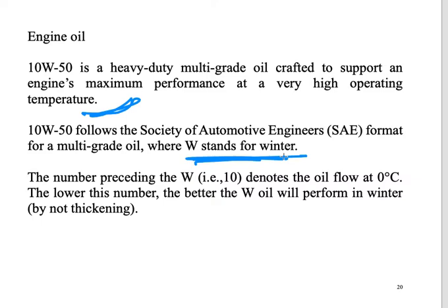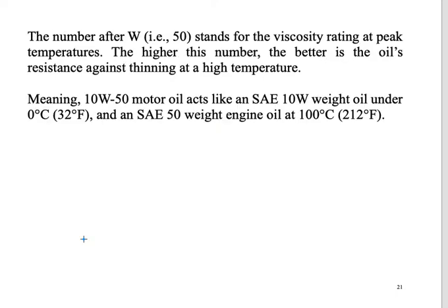So the number preceding the W denotes the oil flow at 0 degrees Celsius. The lower this number, the better the W oil will perform in winter, by not thickening, meaning by not increasing the viscosity. The number after W, 50, stands for the viscosity ranking at peak temperature.